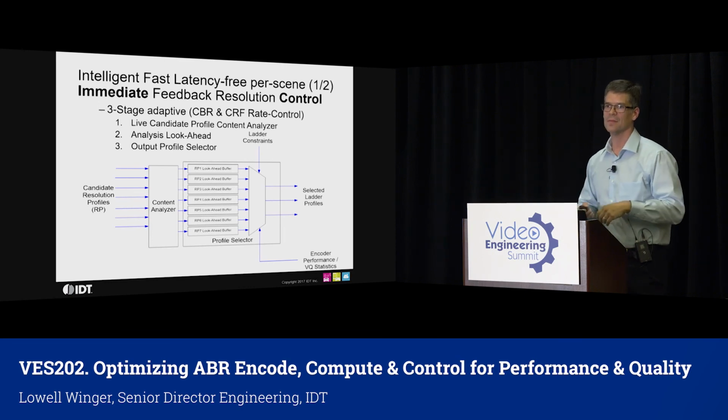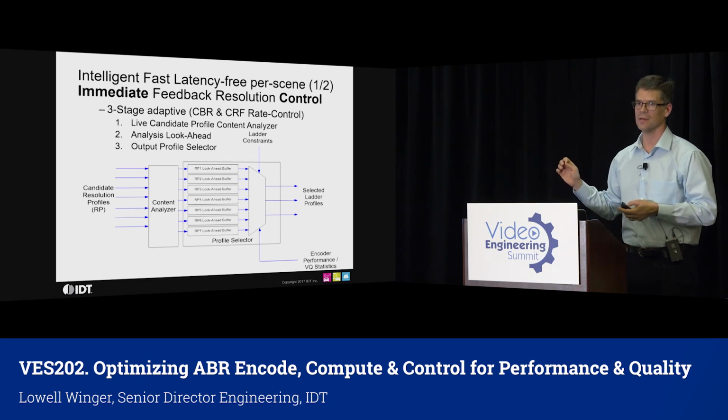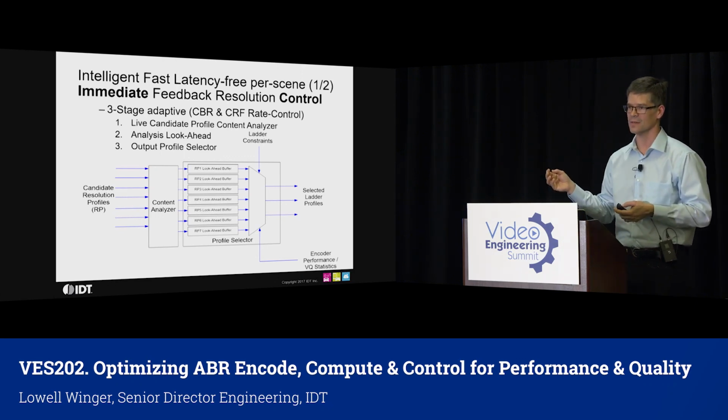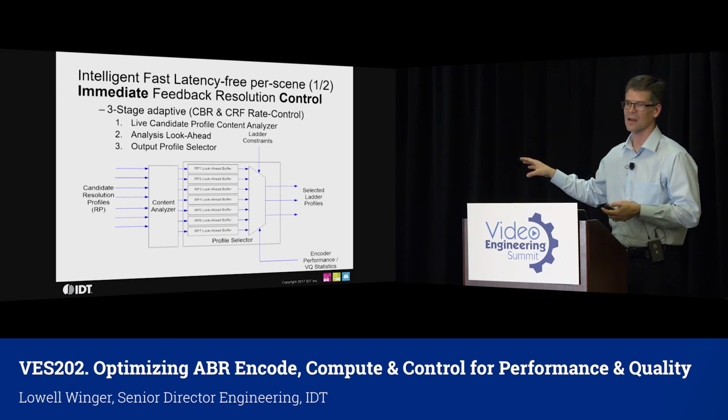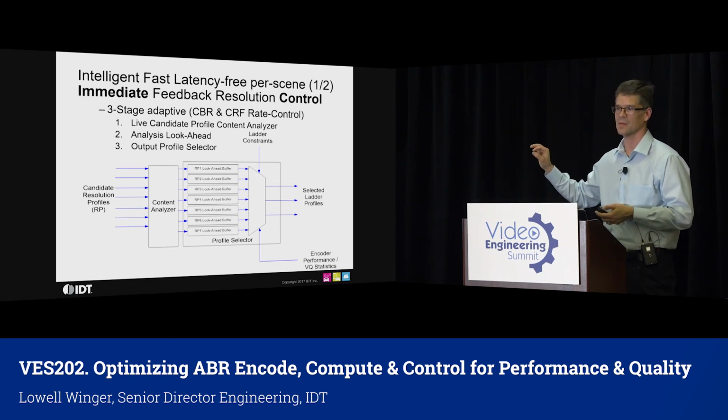Sure. So what we have internal to our encoder is a quantization parameter, which is a rough idea of the video quality. On top of that quantization parameter, you have your visual models, which are like eye tracking models, models that say, for faces and skin tones, you should put more bits into those areas. For text and graphics, you should put more bits into those areas because they're things that people are looking at. Uncovered, covered areas in the video, when a car moves and the road is uncovered, if you're not doing a good job of those, that can be really disturbing to the viewer. So those are all part of the visual model, which is a modulation factor on top of the QP, or the quantization parameter of the encoder.